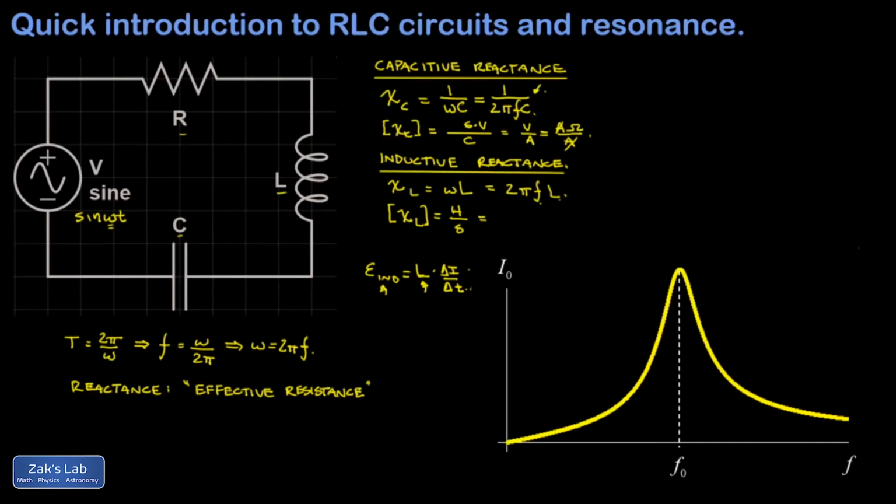And so I'm going to solve for L in terms of all these other quantities, and I would get volts times seconds divided by amps for a Henry. So a Henry is a volt second per amp. Our factors of seconds are going to cancel. And again, I have volts per amp, which I already showed gives me units of ohms. So again, my inductive reactance has units of resistance on it.